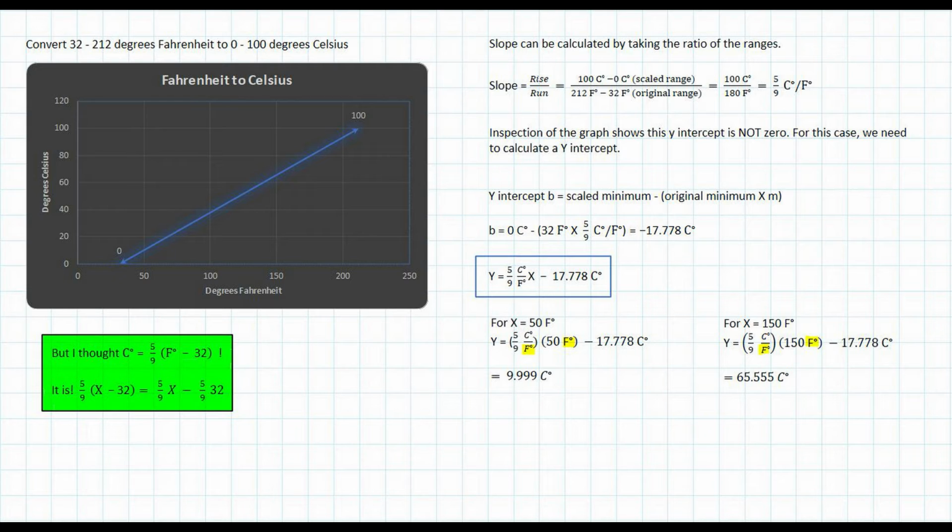When we display this number on our operator interface terminal, we're likely to be rounding it off to a number of specific decimal places. But if our PLC were to, for example, be sounding an alarm when we reached 10 degrees C, then it would be important to make this calculation as accurate as possible by using the fraction rather than a decimal approximation